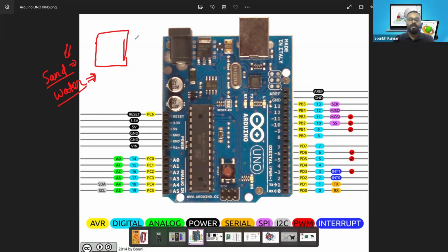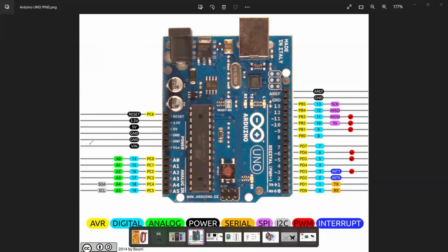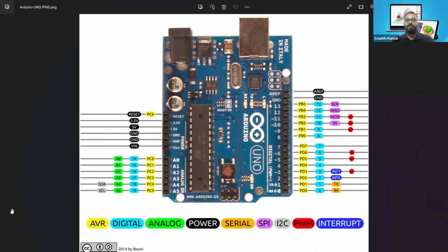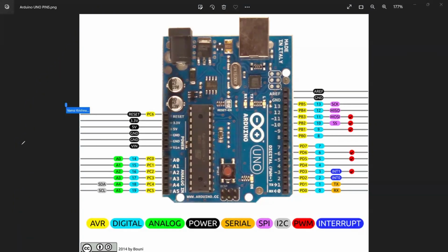Bigger and thicker wheels will be good for your application. Sir, are the wheels just thicker? Yes, for friction. A thicker wheel is a good one that can cross this obstacle. The thicker and grippier the wheel we use, the more friction it will impart, and it will stay in place on our surface itself. Okay, sir.